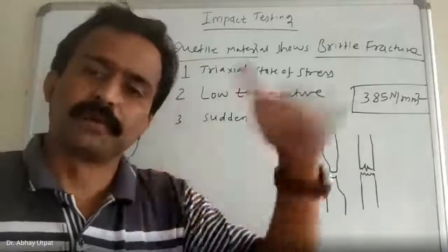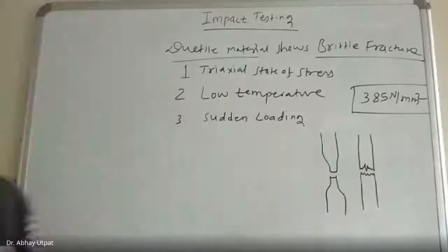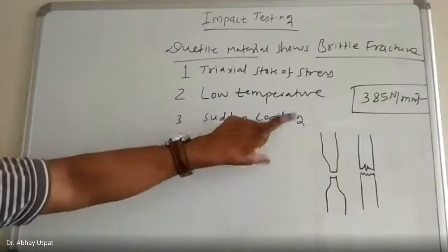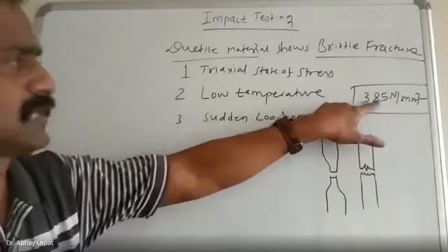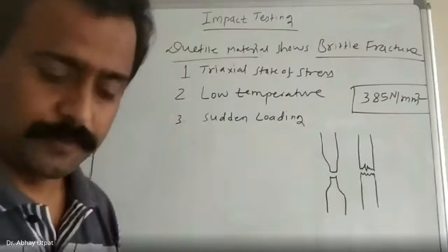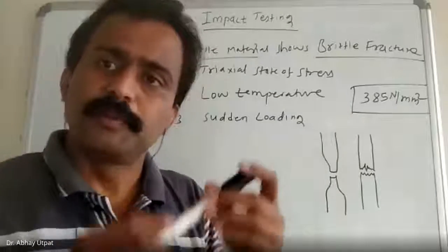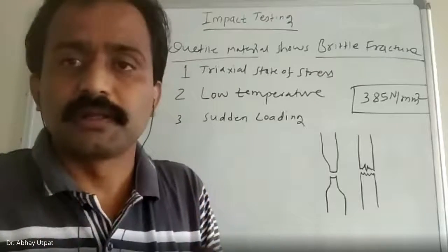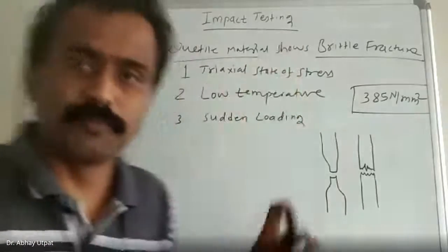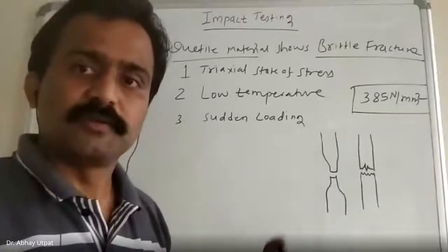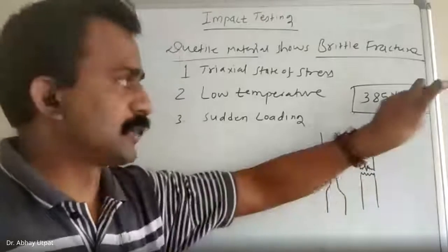Actually, it starts failing above the yield point only, because it shows plastic deformation. Once there is plastic deformation, there is misalignment, etc. Now, as far as this value is concerned, we should not get stuck on this value. You are considering that the part which you have designed may be under tension always. But during working condition, you can't predict; it may come under any of these three conditions. At that time, you can't keep faith on this value.